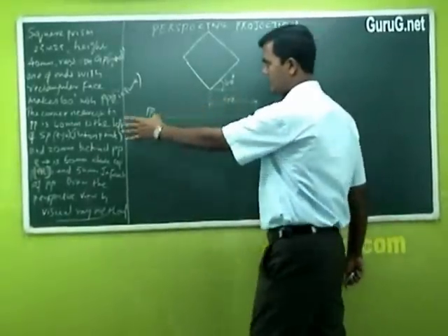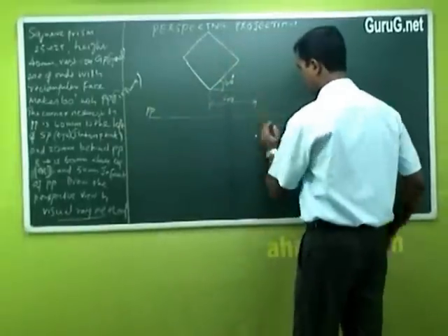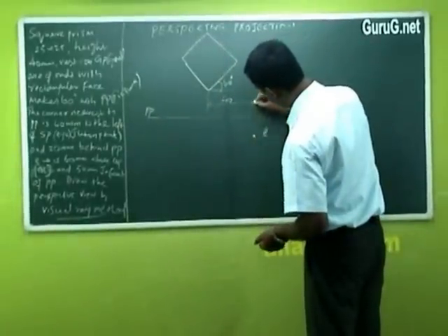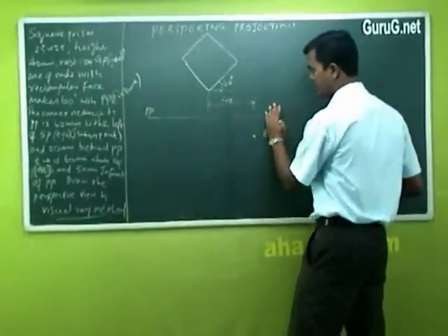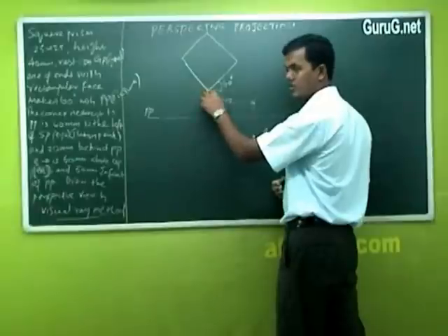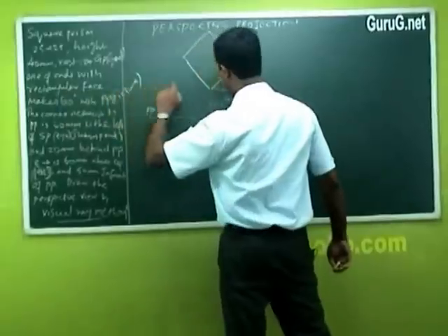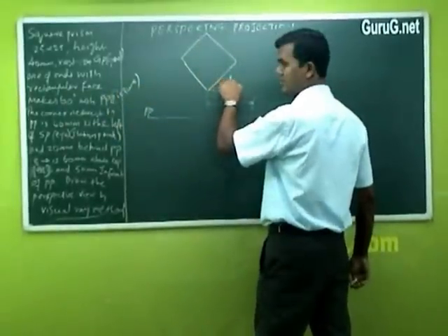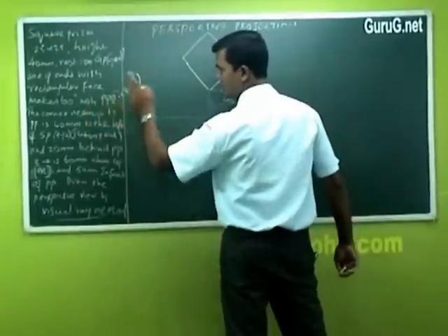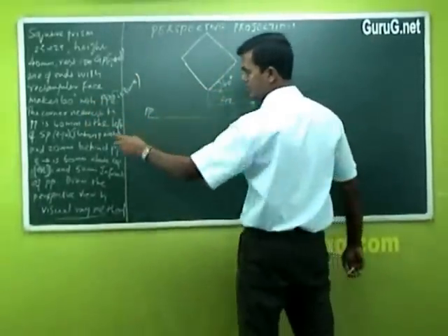So it is 40 millimeter from the eye level point E, the nearest corner to PP. That's one condition satisfied. Fix it here. The second condition is 60 degrees: we made one face at 60 degrees with the picture plane. Okay, so two conditions are satisfied.